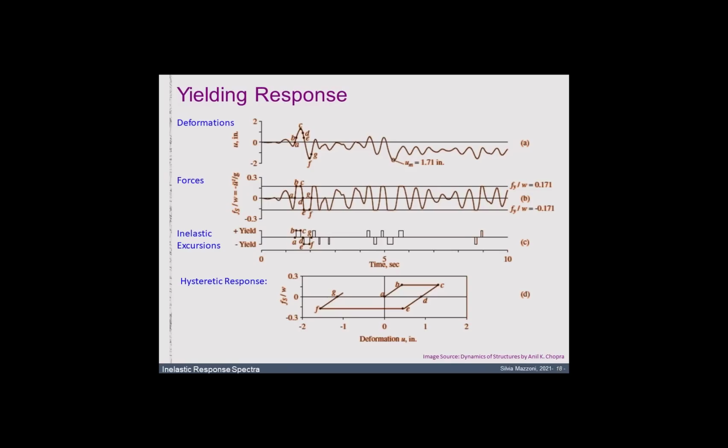And so now we can't plot spectral accelerations anymore. We actually have to look at displacement. What we're used to looking at, pseudo-acceleration response spectra, when we're talking about inelastic response spectra, we're always talking about deformation measures. And I will show you how there's a lot of different metrics that we can look at. Also, the maximum strength demands that you would need for certain deformation requirements.